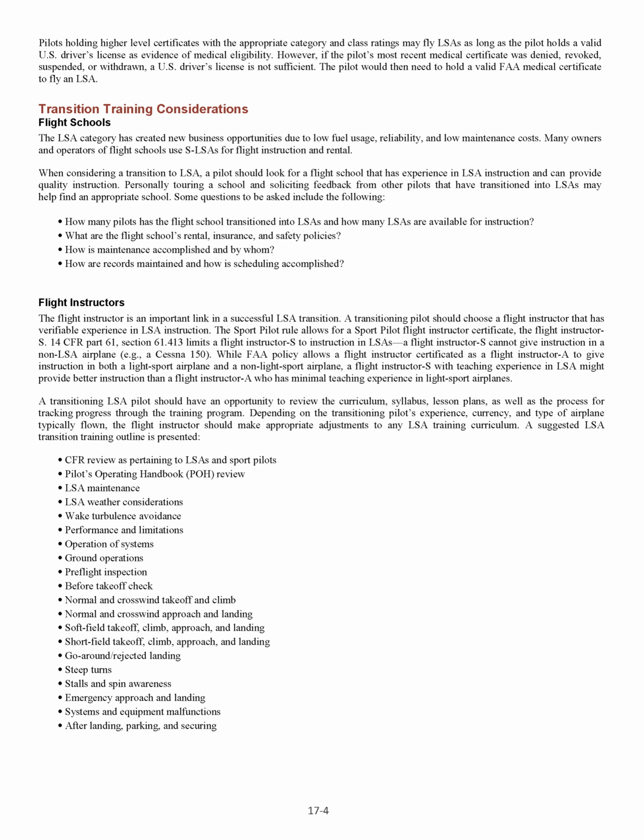Flight instructors. The flight instructor is an important link in a successful LSA transition. A transitioning pilot should choose a flight instructor that has verifiable experience in LSA instruction. The Sport Pilot Rule allows for a Sport Pilot Flight Instructor Certificate, the Flight Instructor-S. 14 CFR Part 61, Section 61.413 limits a Flight Instructor-S to instruction in LSAs. A Flight Instructor-S cannot give instruction in a non-LSA airplane, for example, a Cessna 150.